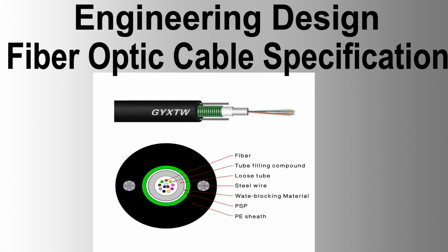Splicing enclosure features must include a guaranteed operational life of 40 years, be physically supported or wall-mounted in manholes, and be equipped with fiber management and protection components. Use mechanical sleeves for all fusion splices, organizing them in a splice tray within the enclosure. Enclosures must include cable hold-down mechanisms, strain relief, and adjustable, reusable cable gland devices to seal against moisture, water, and vermin ingress.